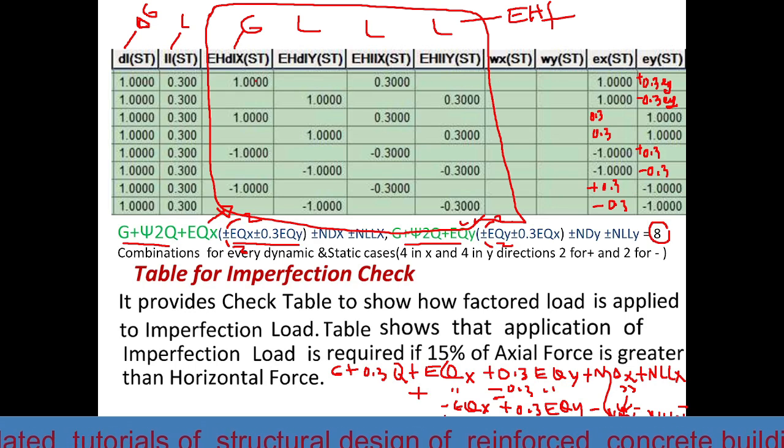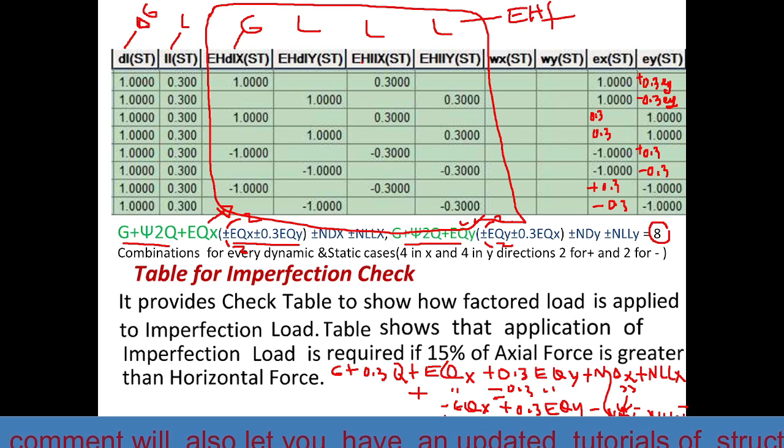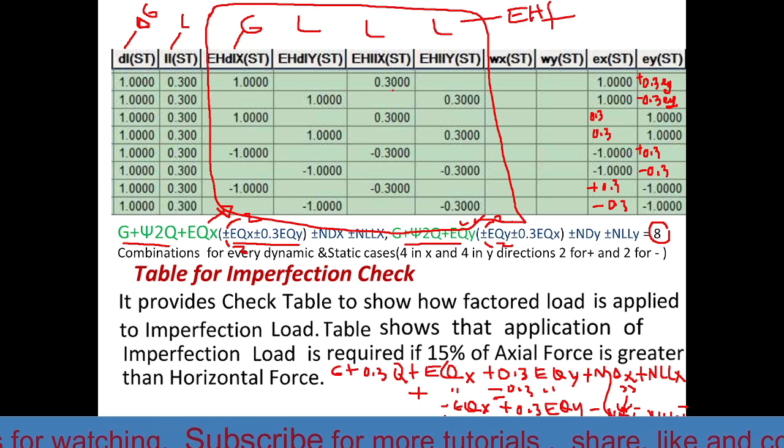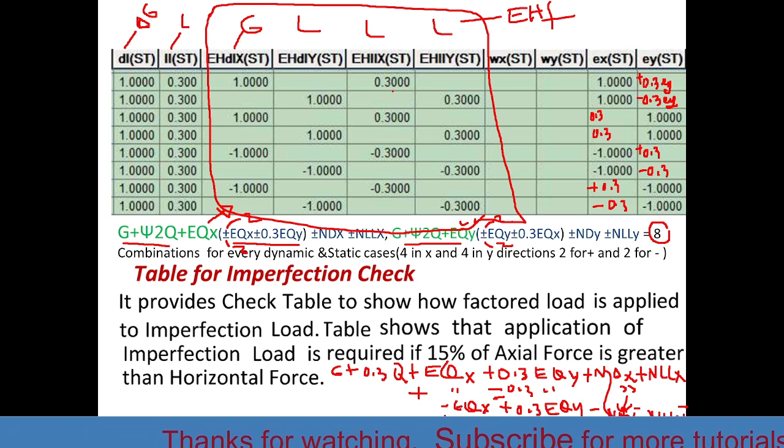So what we are going to take into account is the notional load, or the equivalent horizontal force, which will be applied for every seismic combination.